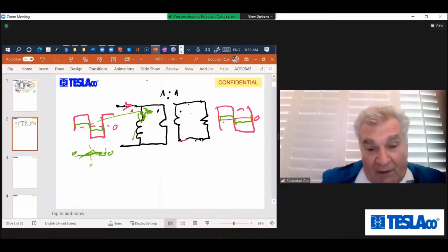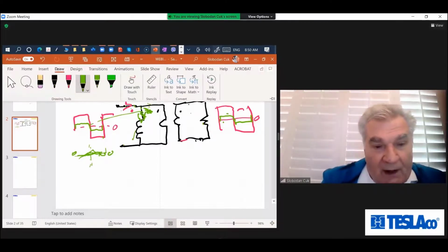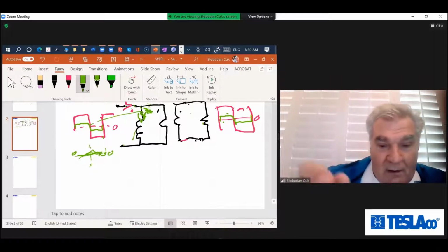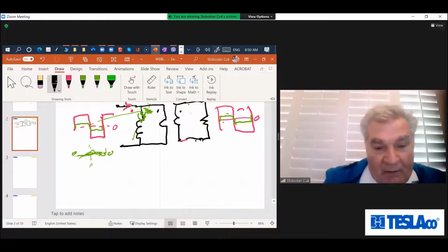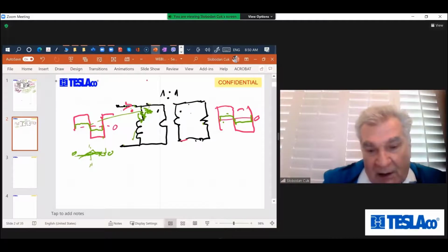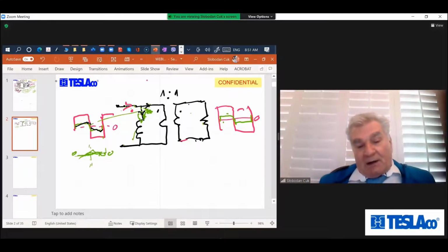Now, when you have this triangular current and reflected square wave current together, what is going to be the current on the input? Then this square wave current reflected on the primary plus triangular current here, these two currents will add together to give a current which has a square wave part plus some triangular part on the other side, right?